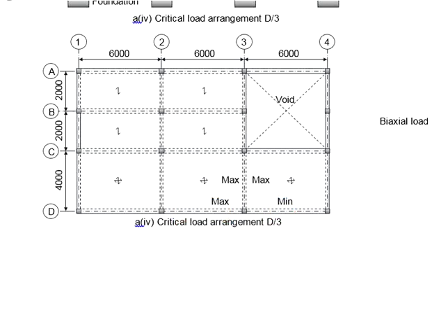How do you decide which should be the maximum and which should be the minimum? Normally, we look at the span. The maximum load should go for the longer span. However, in this case, both spans are the same, so it is up to you. You can have this side maximum or this side maximum. Either way will do. At the end of the day, you will get the same moment.